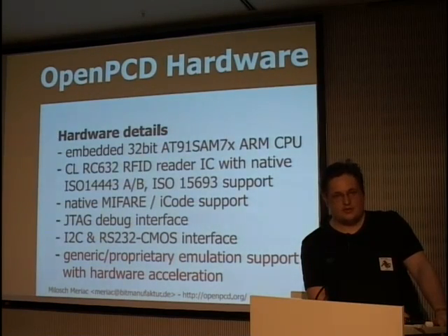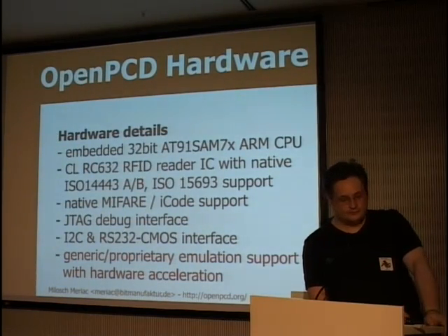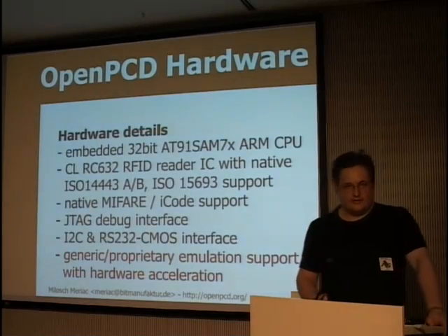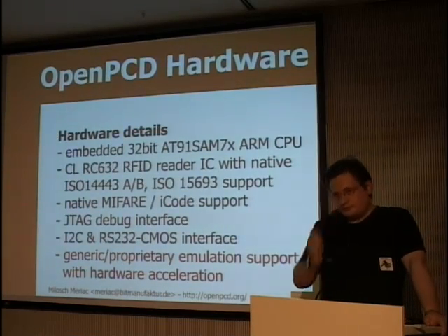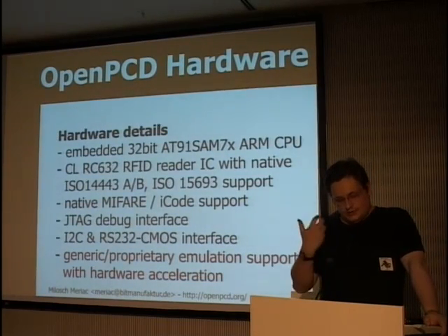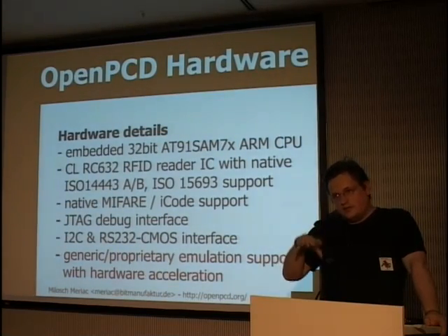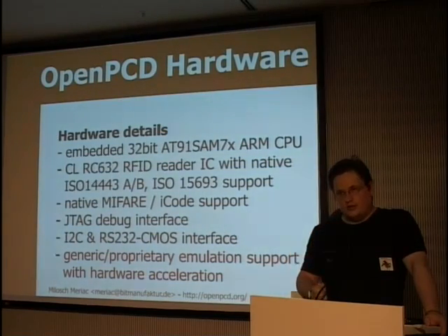For example, with I2C, you can directly attach displays. For example, you can display the name of the person coming in or whatever. Or you can reconfigure the I2C pins to I/O pins. This enables you, for example, to trigger relays and whatever. So all the code can run inside. It fully understands RFID cards. It can do anti-collision. It supports multiple cards in the field. You can even detect what cards are in the field.